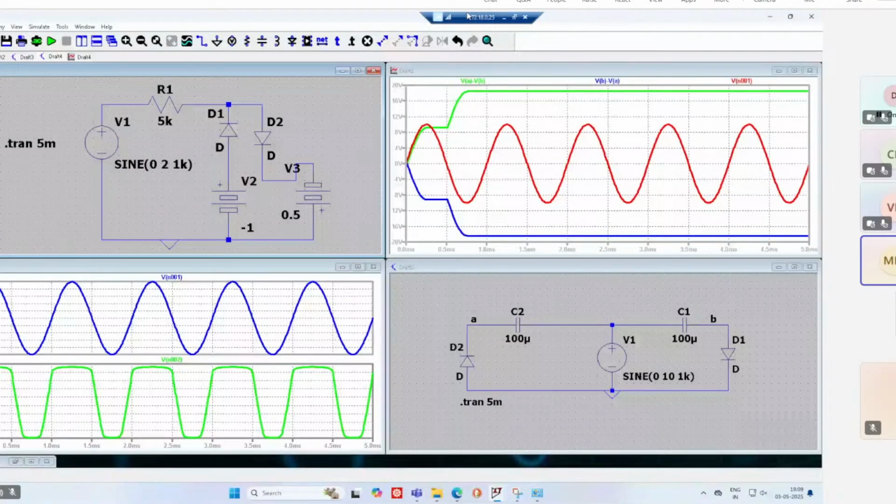Two back-to-back connected diodes in parallel, and then the batteries are also connected. This is the clipper configuration. Clip means clipping away some of the unwanted portion of your input waveform, known as a clipper, right? You might be studying different variants of the clippers. This is one of the typical configurations where both sides of the waveform are clipped away. And these DC supplies,